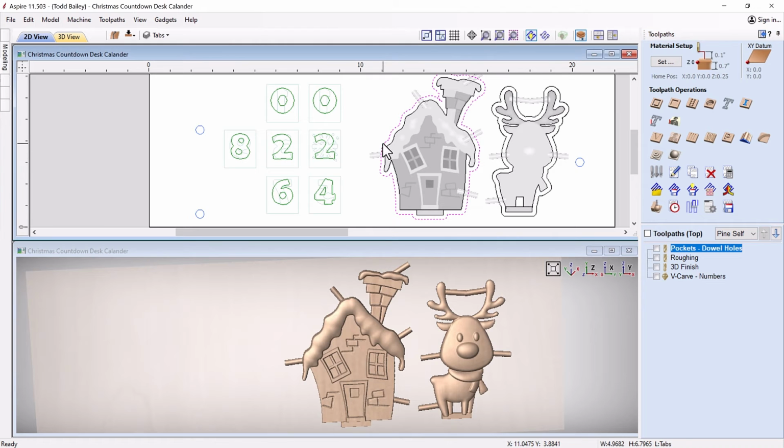And the actual vector I'm going to use to do my roughing and finishing is an offset of the outline of my actual model. So that way I'll get away far enough from my component, and I'll expose these 3D components here of the tabs. And you'll see that in the preview of my tooling in a second.